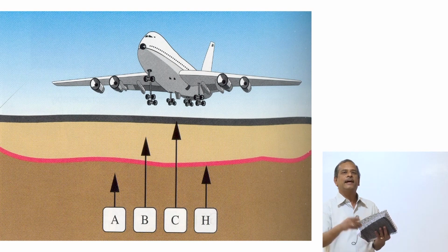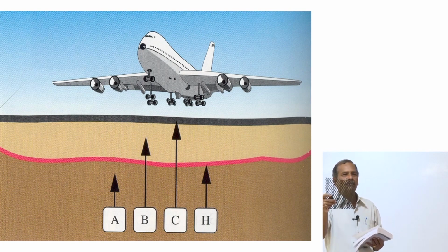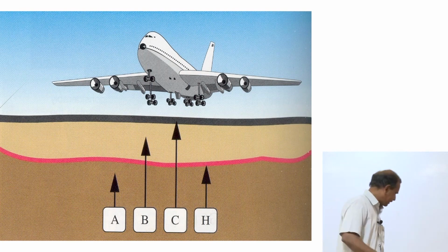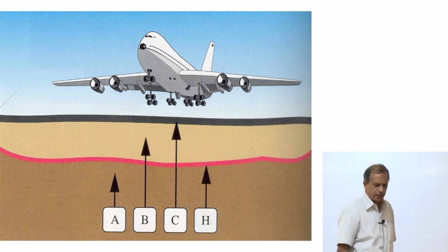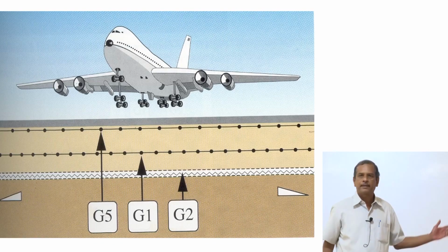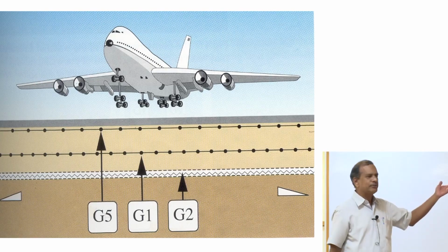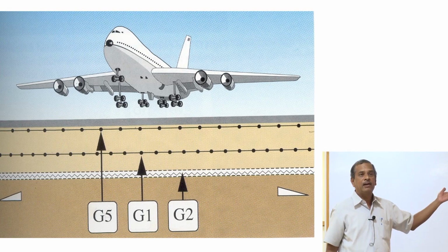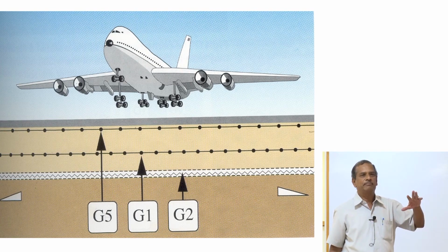So this again has to be done only by a civil engineer. So everything costs money. If you introduce a new material, there's an improved performance at what cost? So I can improve the strength of the subgrade soil by introducing geogrids here. So you can find the 2 layers of geogrids laid there. The runway or a taxiway can last longer without a deformation. No rutting, no cracking will occur.